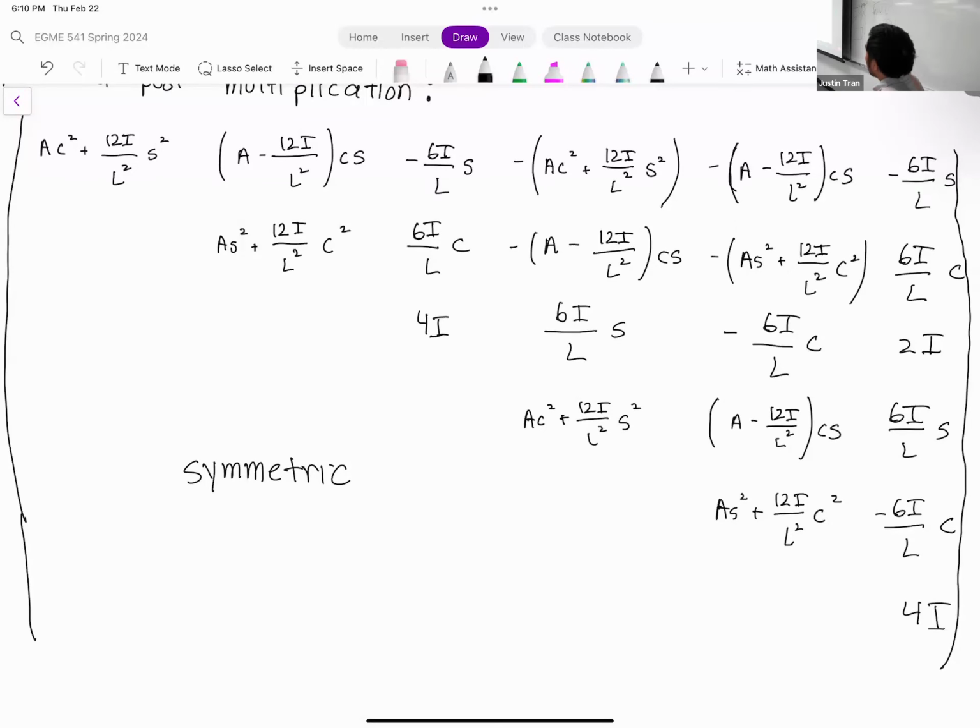All right. So that's our element stiffness matrix for the frame in the most arbitrary sense possible. This is as bad as it gets. This is the worst type of element out there. Obviously, we'll do a couple of examples where these calculations are easy. These calculations simplify quite a bit when your angle is 0, 180, 90, or 270 degrees, because in those cases either sine or cosine is equal to 0. That's going to cancel out a lot of these terms.